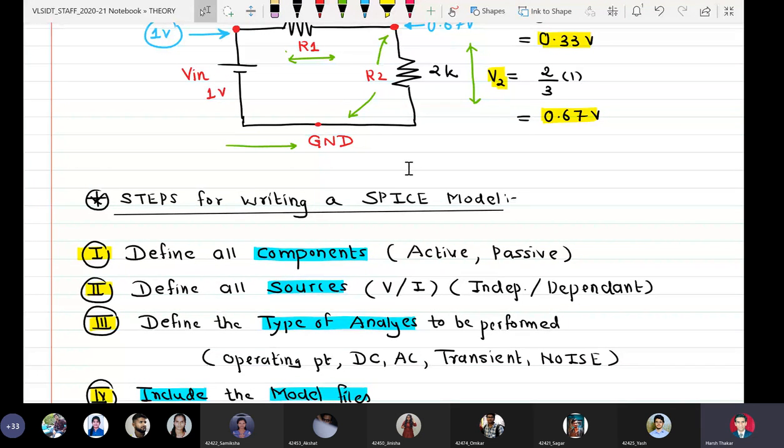In fact, I can tell you that some things which even layout editors cannot do, SPICE has the ability to do. That is why we say that SPICE is a very powerful language, used by PhD researchers to find out, if a certain system has used a certain transistor with certain technical specifications, whether I can find, if I change the width and length or the threshold voltage of a MOSFET to a certain level, what performance improvement I will get.